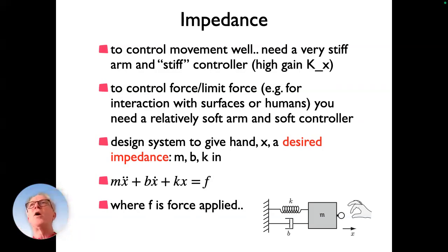So, for instance, if you are guiding a robot arm and moving it around, you might want something like that, so that the forces the robot arm generates in reaction to you are within a definable range, and the rate of change of these forces, like the velocity terms, is of a certain kind, so that you, as a human, can tolerate those.